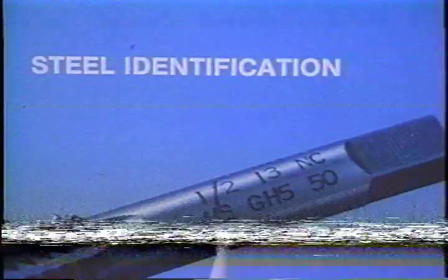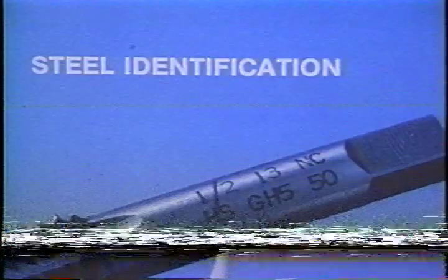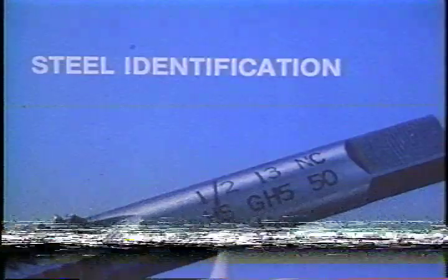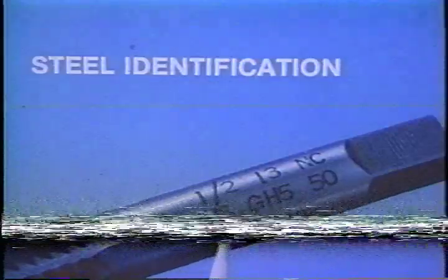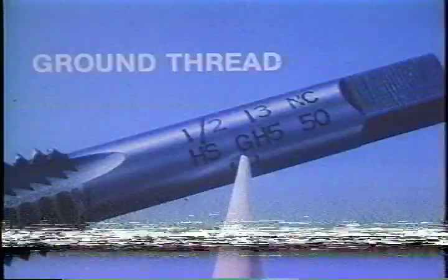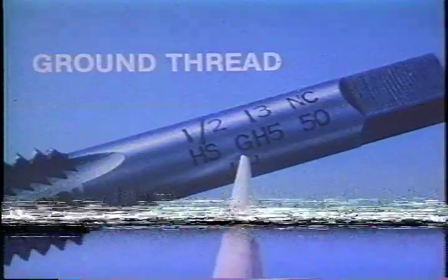Taps are made of carefully hardened carbon steel or high-speed steel. The HS marked on this tap indicates that it is made from high-speed steel. Most standard tap threads are ground for greater accuracy and identified with the letter G.